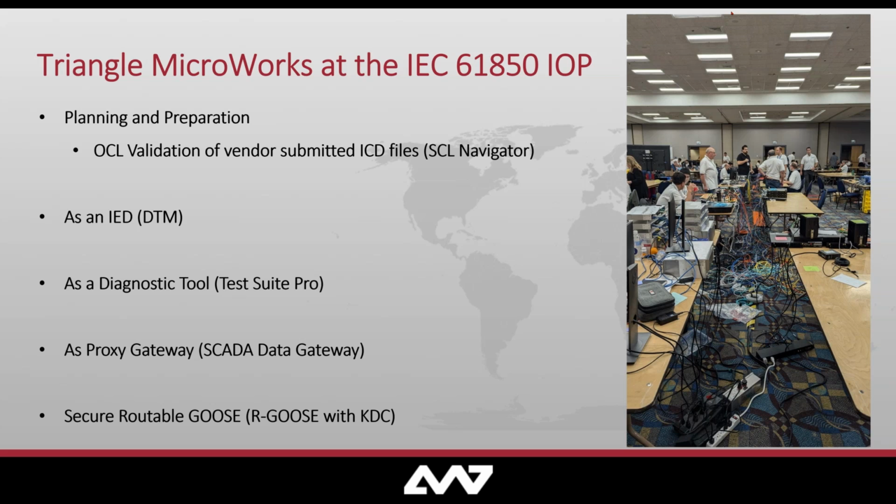Lastly, we were part of the secure and routable GOOSE tests that occurred here at the IOP. These tests assess the ability of both DTM, functioning as an IED, as well as our client testing tool, Test Suite Pro, to both send and receive routable GOOSE messages. The key was to ensure that these messages, which had security enabled, had authentication and encryption that could be authenticated and decrypted by other devices receiving them, and of course that our tools could do the same thing for messages sent by other vendors.